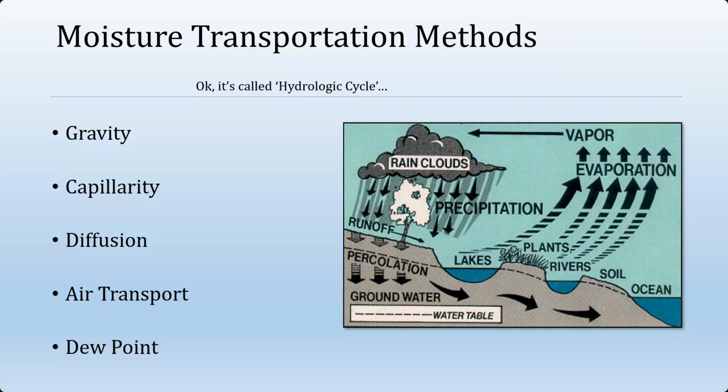The dew point typically occurs at, around, or generally within the primary thermal layer. If we place all of our thermal layer, our insulation, on the outside of the foundation or the above grade wall sections in the form of a closed cell foam plastic, the dew point's generally going to occur largely, I always say largely, within the primary thermal layer. This type of closed cell foam plastic, the pink and the blue stuff, has a finite amount of water absorption by volume, usually not much more than, I believe, 0.1% by volume, expressed as a maximum.